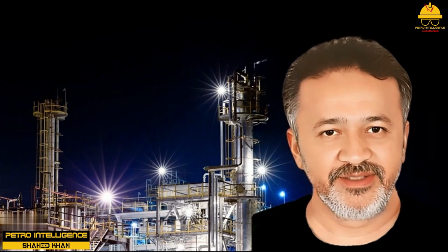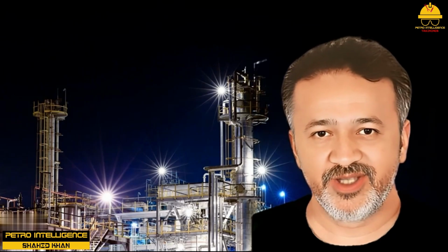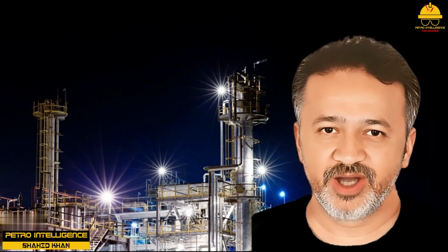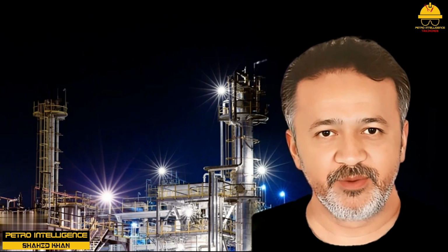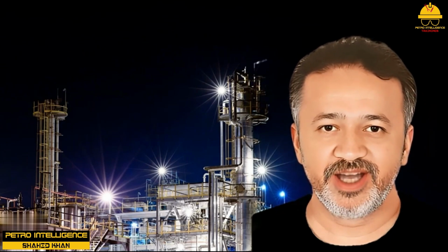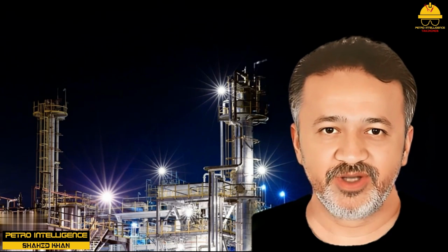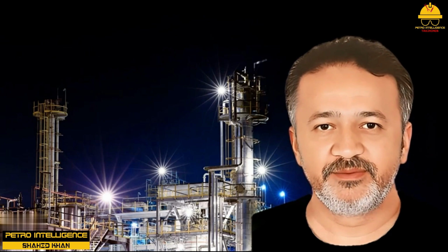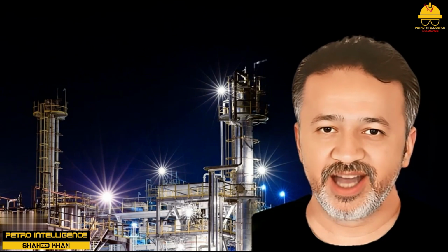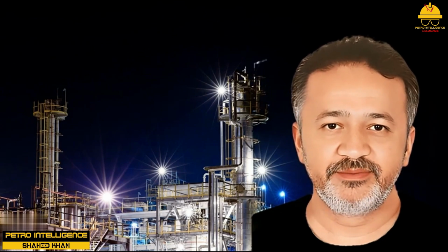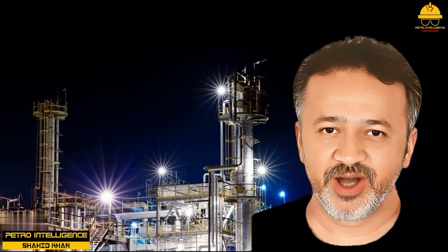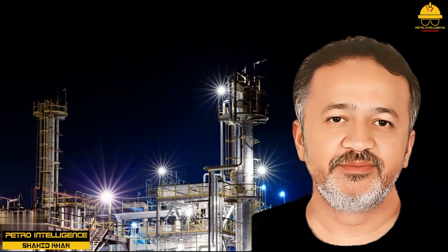Replacement reactions. Industrial manufacturers use replacement reactions to remove dissolved mineral ions from process water. A number of dissolved minerals can be found in process fluids. A common compound found in process water is calcium chloride. Calcium chloride forms positive calcium ions and negative chloride ions when it is dissolved in water. A replacement reaction can remove the calcium ions and the chloride ions with synthetic resins.